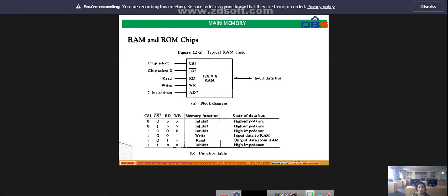Next is the dynamic RAM. What is meant by dynamic RAM? The dynamic RAM stores the binary information in the form of electric charges that are applied to capacitors. The capacitors are provided inside the chip by MOS transistors. The stored charges on the capacitors tend to discharge with time, and the capacitors must be periodically recharged by refreshing the dynamic memory. The dynamic RAM offers reduced power consumption and large storage capacity in a single memory chip.